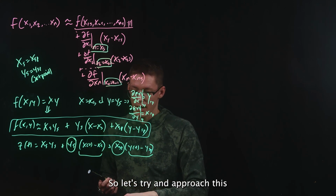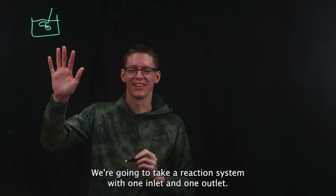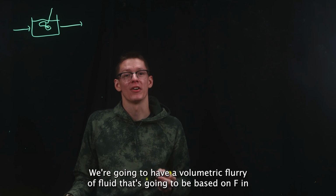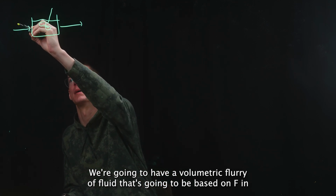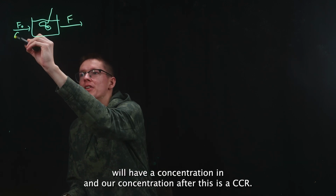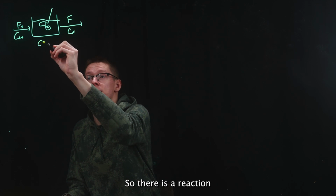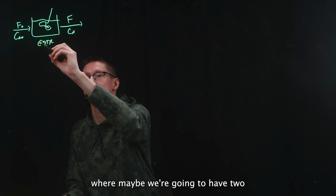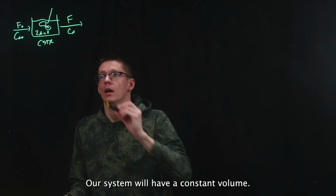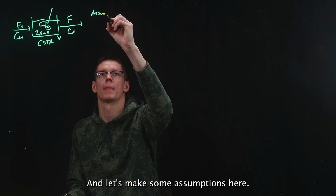So let's try and approach this with an actual model from our course so far. We're going to take a reaction system with one inlet and one outlet. We're going to have a volumetric flow rate of fluid that's going to be based on F in and F out. We'll have a concentration in and our concentration after. This is a CSTR, so there is a reaction where maybe we're going to have two A's making a product. Our system will have a constant volume, and let's make some assumptions here.